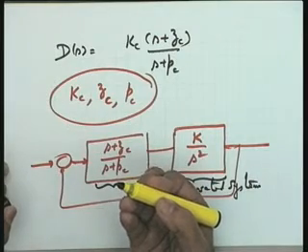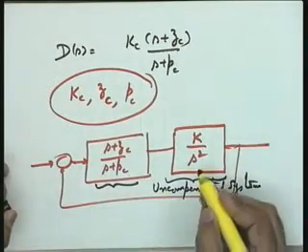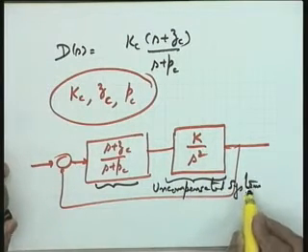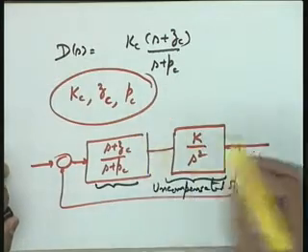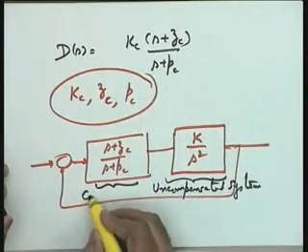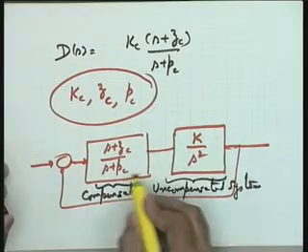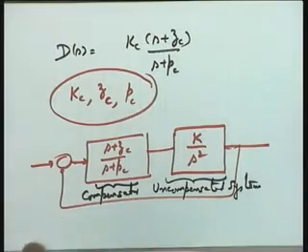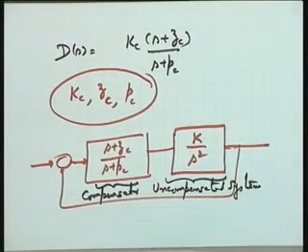So I think I have quite emphasized, or maybe overemphasized, my point that this is only to set the design sequence in order: that the uncompensated system is given by K into a transfer function, where K is an adjustable parameter, and the compensator is given by (S plus Zc) over (S plus Pc), where its gain has been taken as unity for the convenience of the design procedure.